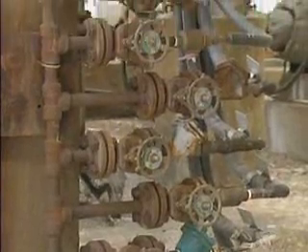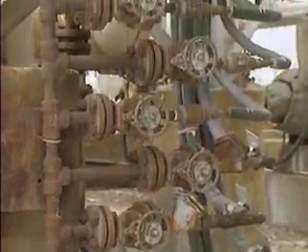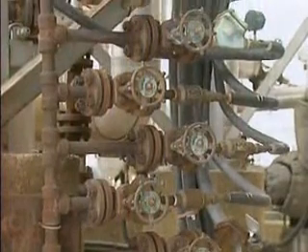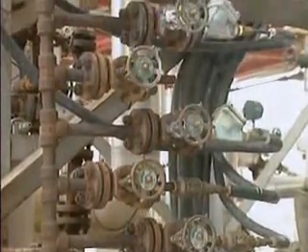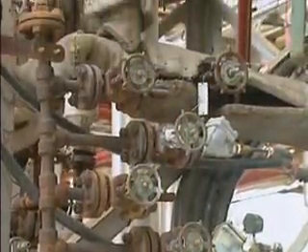After a steam trap station has been surveyed or inspected, the next step is to survey the individual traps in the station. Trap problems aren't always easy to detect, so a combination of different inspection methods may be used. Typically, a thorough trap survey combines information obtained by performing 3 types of inspections: temperature, sound, and visual.